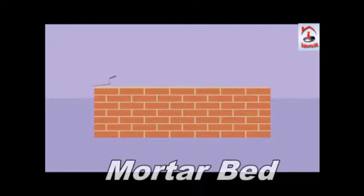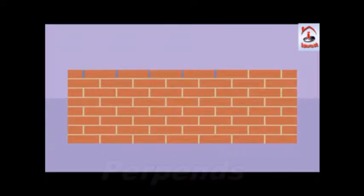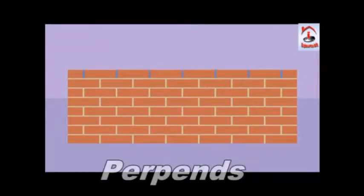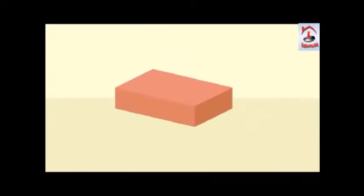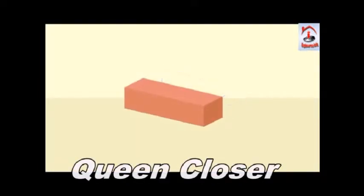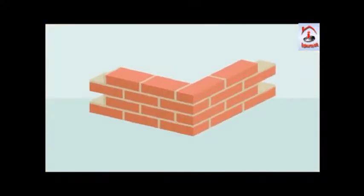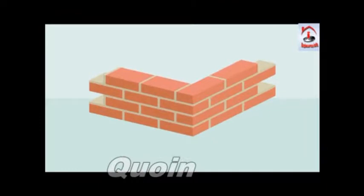A mortar bed is the layer of mortar on which a course of bricks is laid. A perpend is the vertical layer of mortar at the joint between two bricks. They ensure that bricks in the same course are held together. A queen closer is a brick cut in half lengthwise. The quoin is the corner brick where two walls intersect.